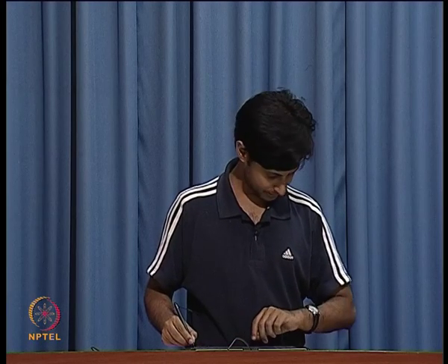So, you go to the market and you want to buy some cables, make sure that what you buy, if you are buying for your lab, is a 50 ohm cable and not 75, because 75 is very widely available. All right.